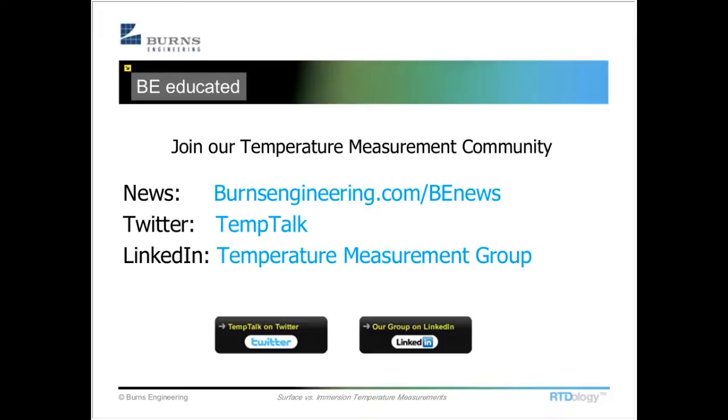Okay, and one other question here. Can you recommend any solutions for induced noise in the feedback signal for RTDs, i.e. motor winding RTDs for motors using a variable frequency drive? Yeah, I guess there's no real good solution for that. Shielded cable is about really all you can do there. Really not any other way to look at that, at least that I know of.